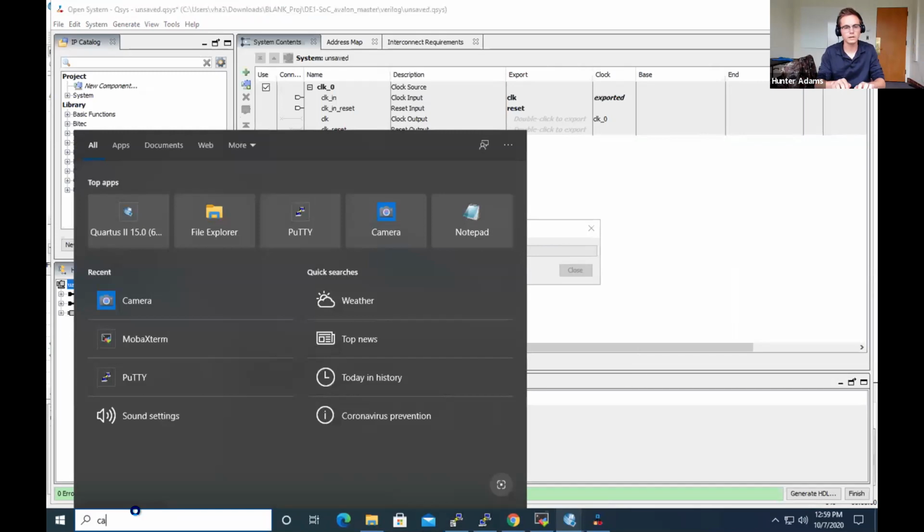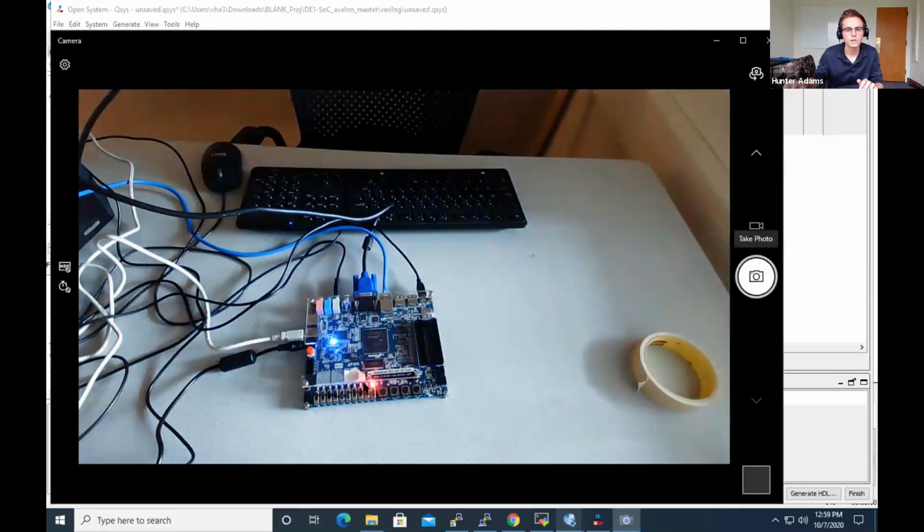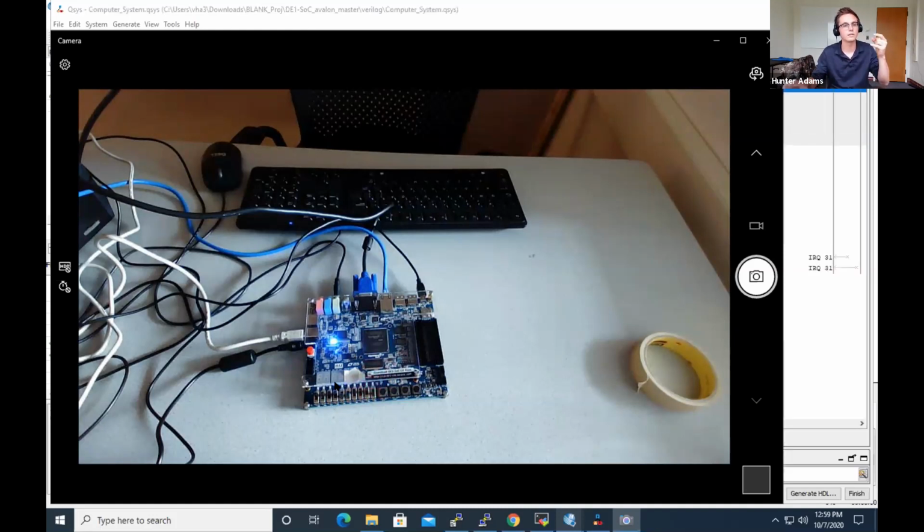And I believe I have this already on the FPGA. Yeah, so this is just blinking at approximately 1 hertz. And what I want to do is set up a few PLLs to blink these other LEDs at faster rates. So we'll essentially copy paste the Verilog that we already have in there, but instead of running it off of clock 50, we'll run it off of our own faster PLL and see that the adjacent LEDs blink faster. And we'll do that in a few different ways.